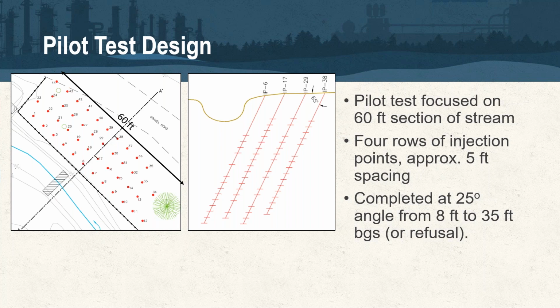One follow-up question that did come through during your answer relates to injecting through existing injection wells on the site. We cannot inject through existing cased wells when we're talking about overburden or even consolidated lithologies, because we are injecting solid particles.